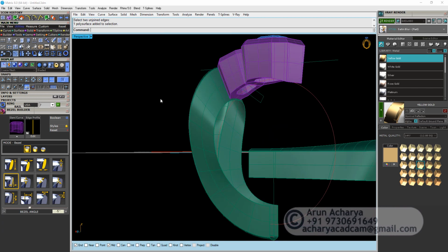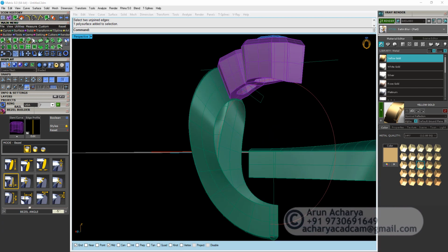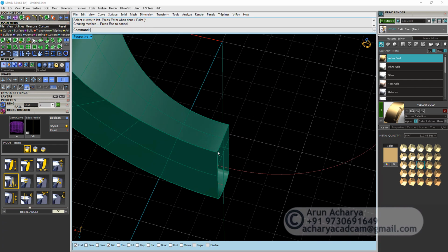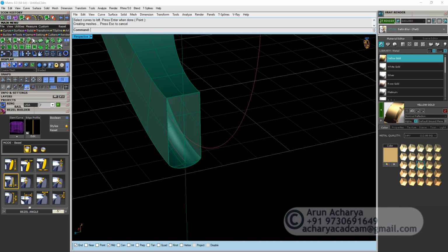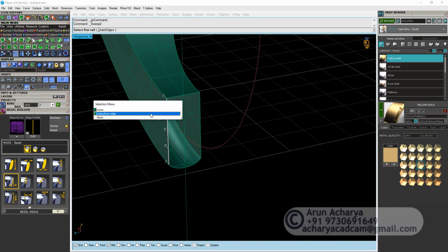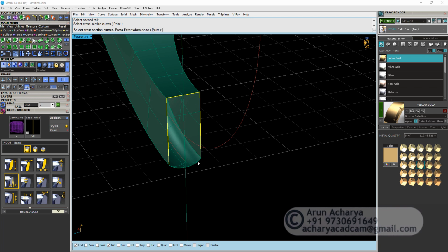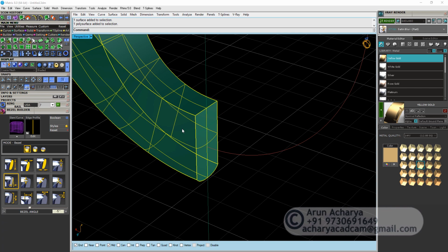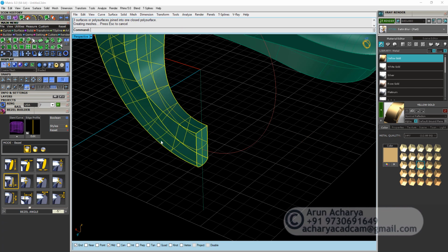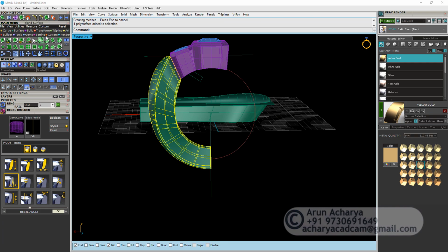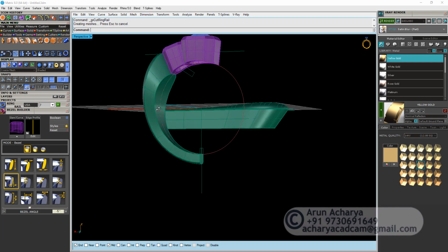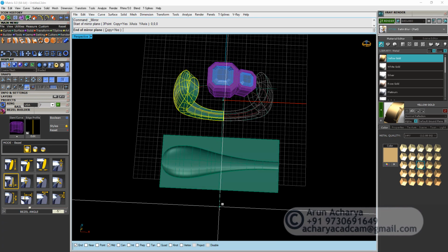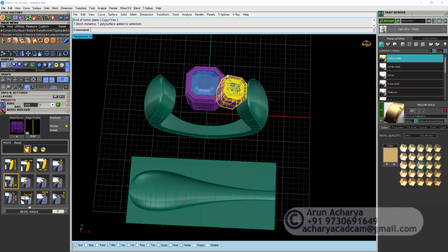Okay, perfect. Then over here I'm gonna just do a loft between these 2 surfaces, and here I'm gonna do a sweep tool, so edge, edge, edge, and this edge over here. Okay, now the only reason I'm closing this is so that I can have 1 closed polysurface and chop this off with my ring ID. Okay, so that's the idea over here. And let's just mirror this on the other side along with this one.